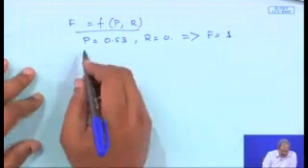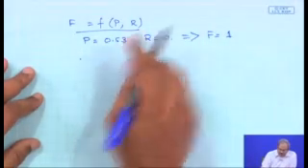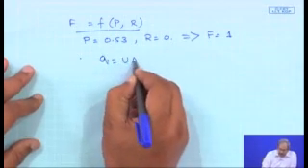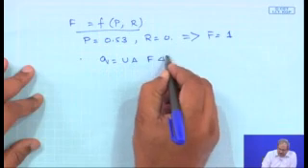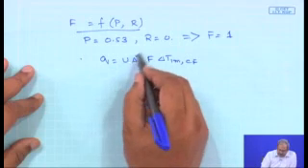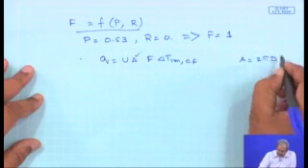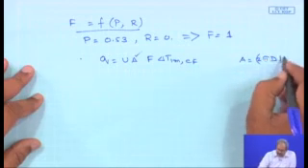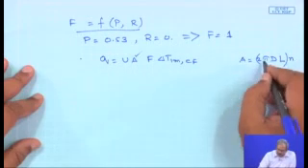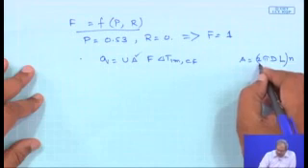So, if F is equal to 1, then from the expression Q is equal to U A F delta T log mean based on counter flow, this A is simply going to be equal to twice pi D times L, that is the area of one pipe, multiplied by 2, considering it is spanning 2 times.